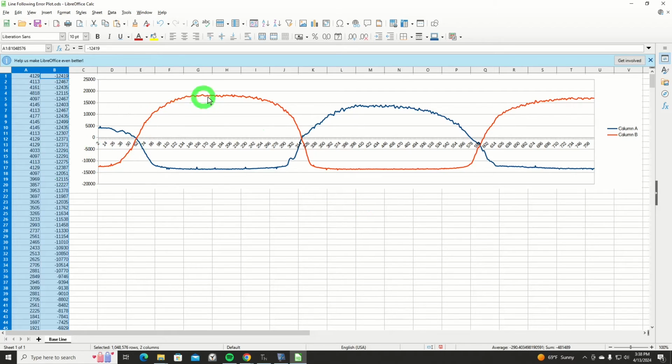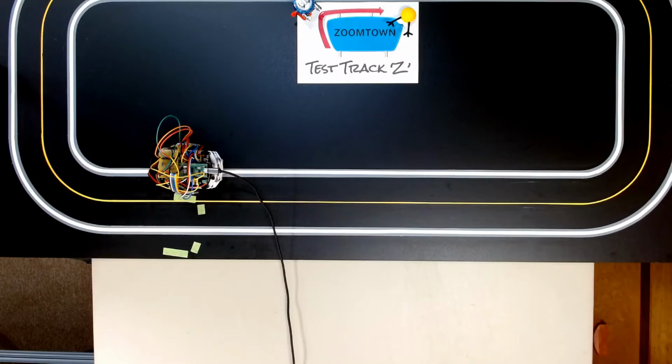It's just wandering too far into this direction, then it starts the course correction, and it's so slow that it can't get caught up. When it starts changing, it goes too far. It's just taking too long to do anything. So I'm going to go back to that 0.0001 value and then tweak up or down from there.